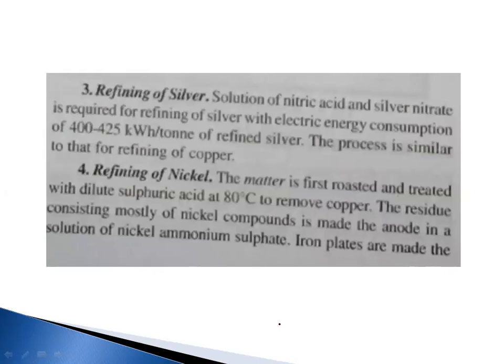Third, refining of silver. Solution of nitric acid and silver nitrate is required for refining of silver with electric energy consumption of 400 to 425 kilowatt hour per ton of refined silver. The process is similar to that for refining of copper.